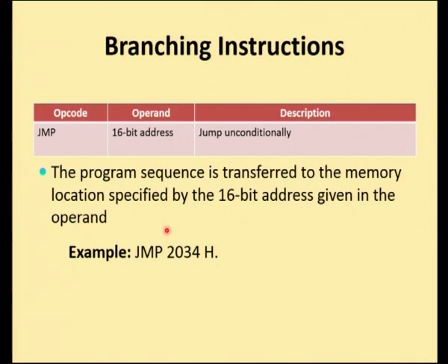Then the address where to switch over will be loaded in the program counter. Now, the program counter will start with the new instructions. After reading a return instruction or after meeting the condition, it will pop the previous address from the stack, then it will return back to the main program. That is the main function of the branching instruction.